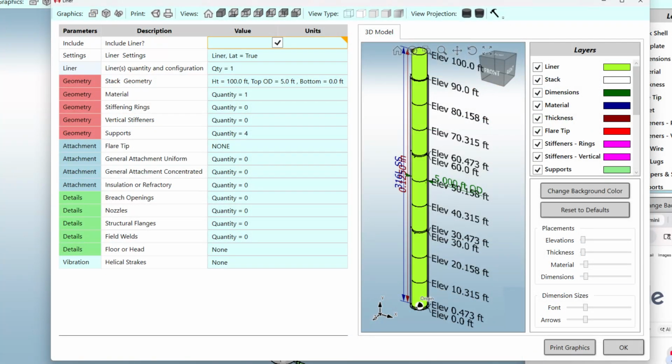The software does not automatically consider the relationship between these two connections and consider any radial or longitudinal differential thermal expansion. In general, the software does not consider tolerances or interference between the liner and main stack. The graphics will give some visual clues when there are problems, but please do not assume that the software will address all potential interference issues that might occur.